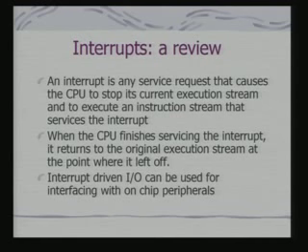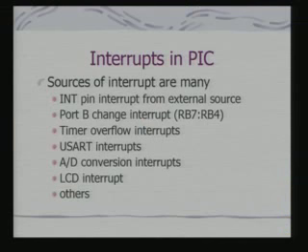The CPU stops its current execution and it starts execution from a different instruction stream which is targeted for handling the interrupt. And when the CPU finishes the interrupt, the execution returns to the original program. We shall see how this mechanism is really implemented in PIC.